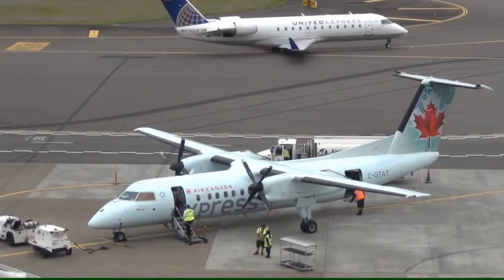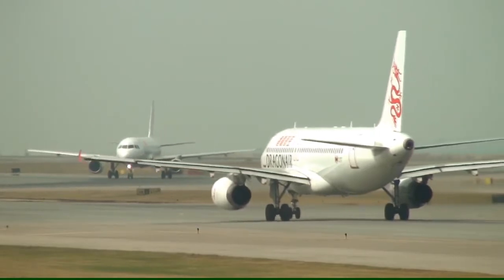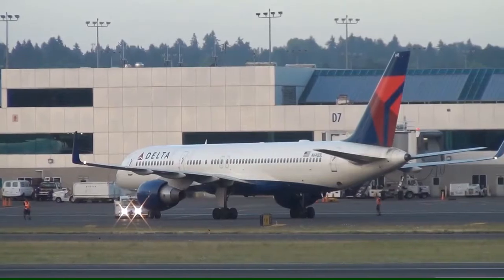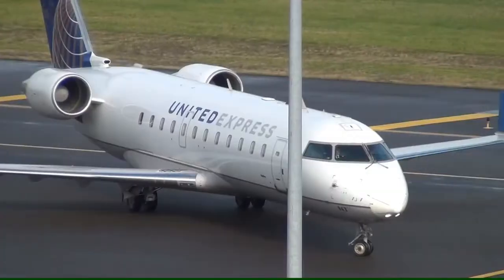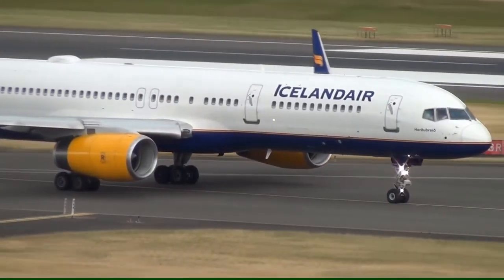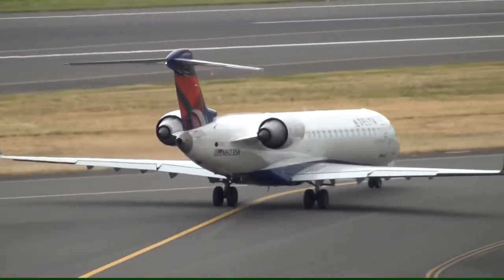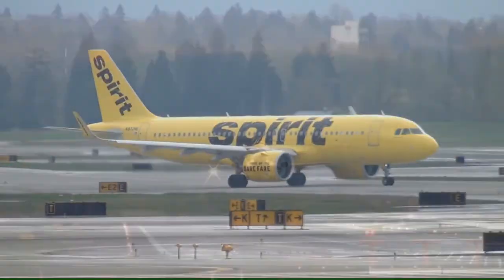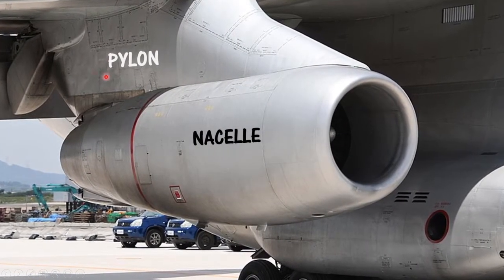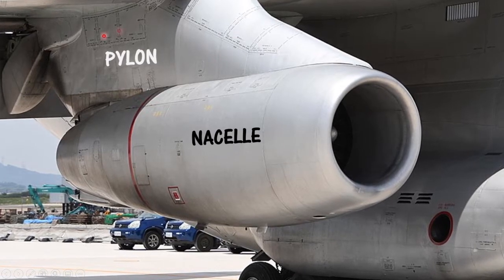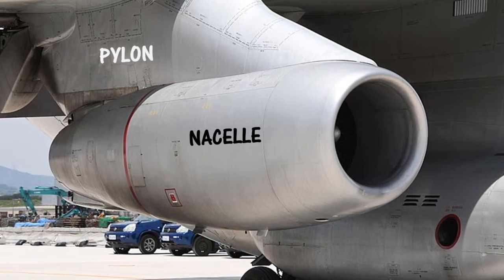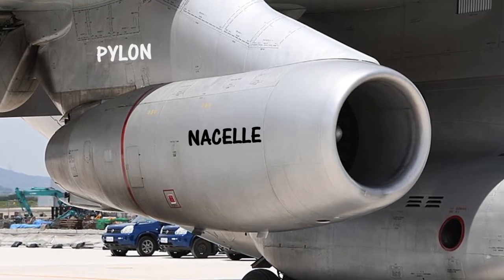Here we look at the major components of the overall system. Engines, including their own systems, have valves, fuel and oil pump, and engine control computer. Engine buildup has hydraulic system, electric generator, engine bleed for cabin air conditioning and fuel line. Pylons are the structural link between the engine and the wing. All the forces are transferred through it, including the engine thrust that propels the aircraft. All systems are routed between the engine and the aircraft and host certain equipment such as fire extinguishing bottles.